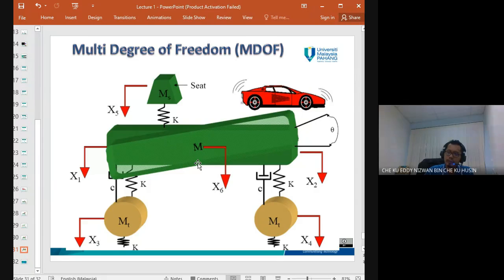The same goes when you design a baseball bat, for example. With a good design, when you hit the ball, the reaction force received by your hand is less. That's the same concept, which we call the center of percussion. For more detail, you can study another degree of freedom to model, which is to measure the angle, so the rotational motion.